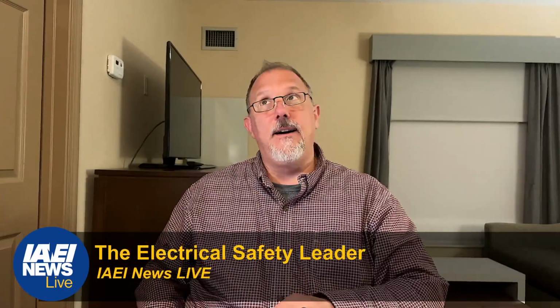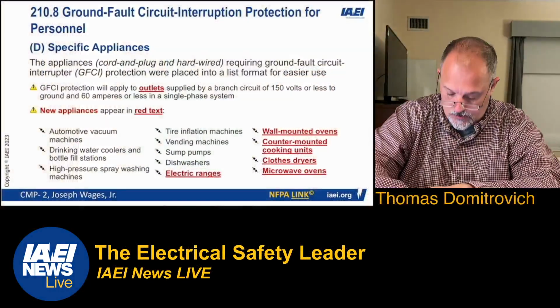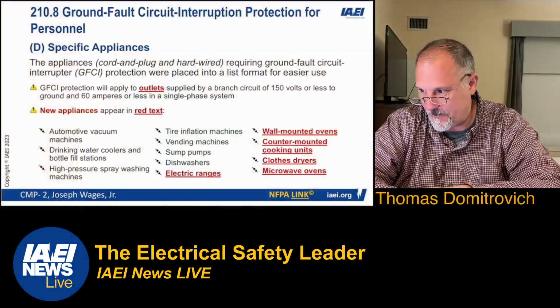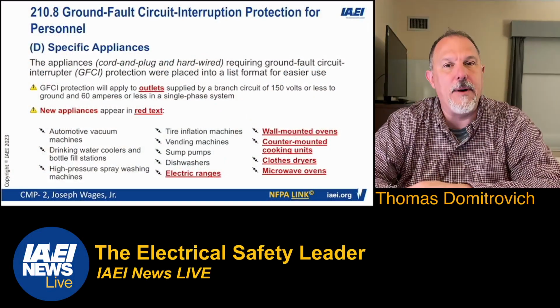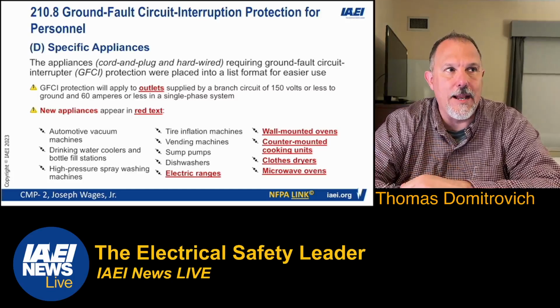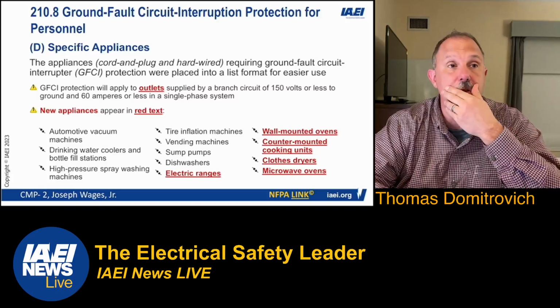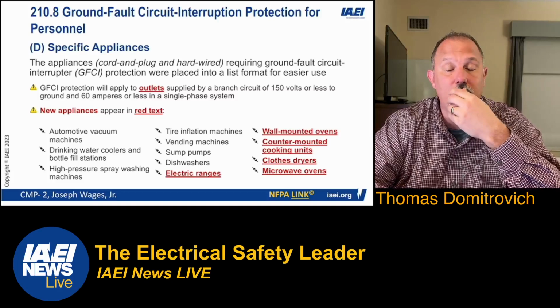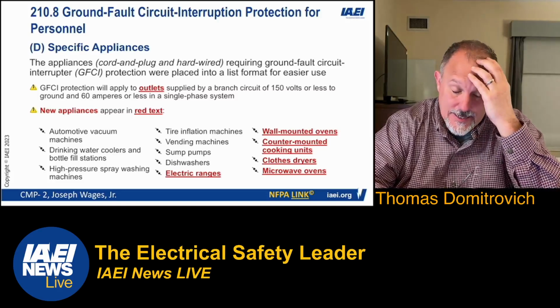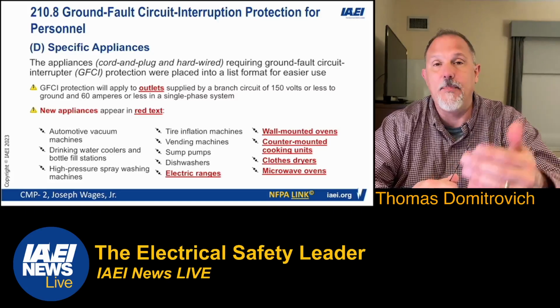And in D, so we had a discussion in 210.8(D). Remember, we're here about appliances. The argument that I've heard over the last two cycles from different individuals, either when we were doing educational programs or even at the table, we've had people make these comments. They said, look, this is what they'll do. They're going to take the cord of that appliance.